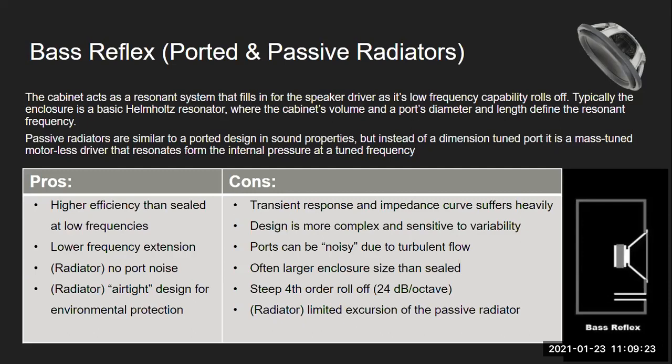The problem is that you have to design it so that it has more displacement ability. Technically, it should only have to match the displacement of the active driver, but typically you want to have, I think, at least 30 to 40% extra displacement available, so that you're not at those nonlinear mechanical limits of the radiator design. So that's a fun one.